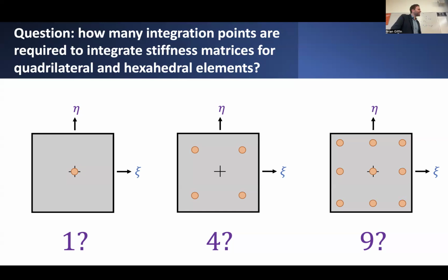Well, it's kind of hard to answer this without actually going through the steps and figuring out what we actually need out of the stiffness matrix. Could we get away with this? Could we just say we're approximating this integral at the end of the day, and it's all going to be approximate? Certainly, if we throw enough integration points at it, we're going to converge to the right answer. And that's an important point, that we could theoretically throw an infinite number of integration points at this thing, and as long as it's a consistently defined integration rule, we should still converge to the same answer.